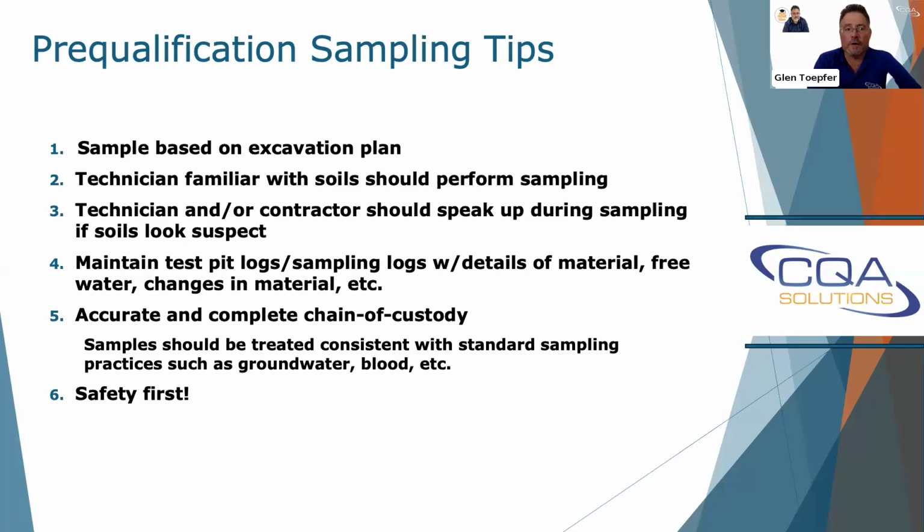You see contractors dig in the pit, they dig some kind of junk out of there, and they never say anything about it. And the technician doesn't either. And I end up having to resample and do other things. Maintaining good logs, whether it's your test pit logs, sampling logs, details, free water, things like that.